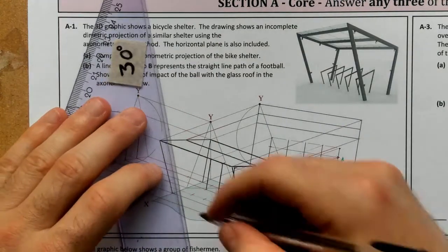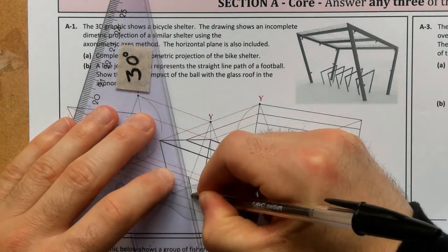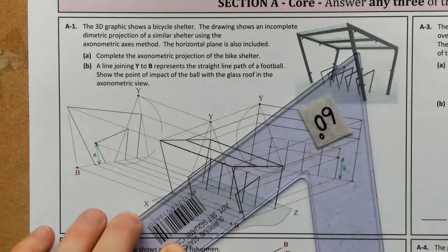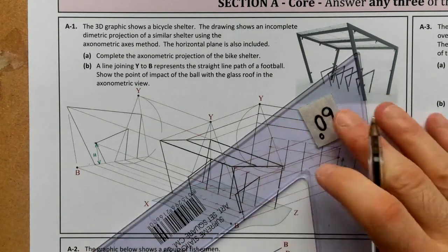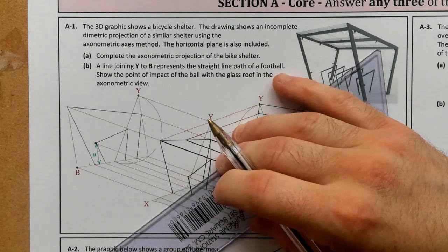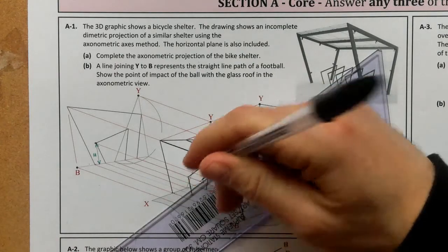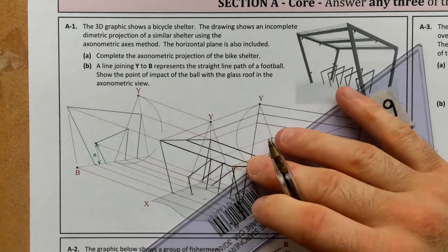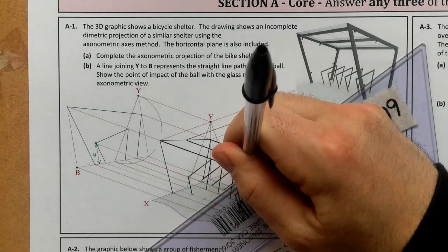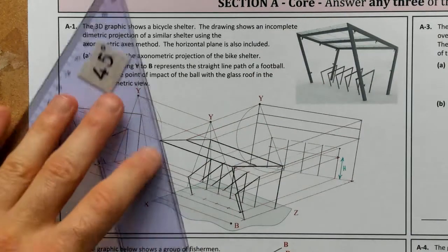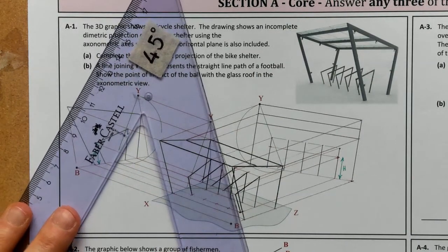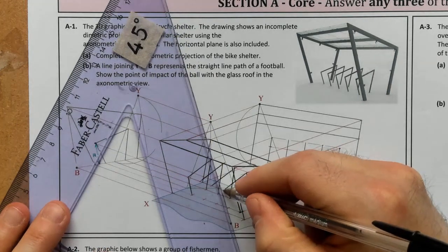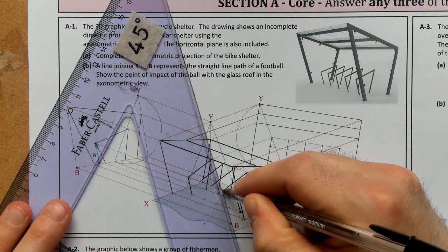So now it's a case of heavying in. Okay, you could do, as I said, get a sliding set square, save a bit of time rather than switching around the whole time. And as I said, they should match up. Okay, you can see all of them are matching up. And this guy here, because the line is so short, sometimes it might be a bit off. Just check it 100%, be happy with it before you do it.